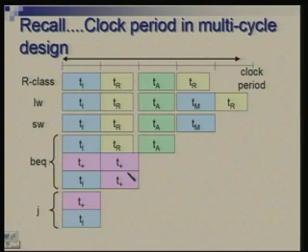These were the timings we had conceived earlier, and we were actually imagining the time for jump to be just this much. So, basically the first clock period which will accommodate T plus or T I would be used, but we are doing something now, a very simple activity. Since the time is quantized, discretized in terms of clock periods, we need to go beyond this and we can't use anything less than a cycle. So, we use 2 cycles for this instruction.